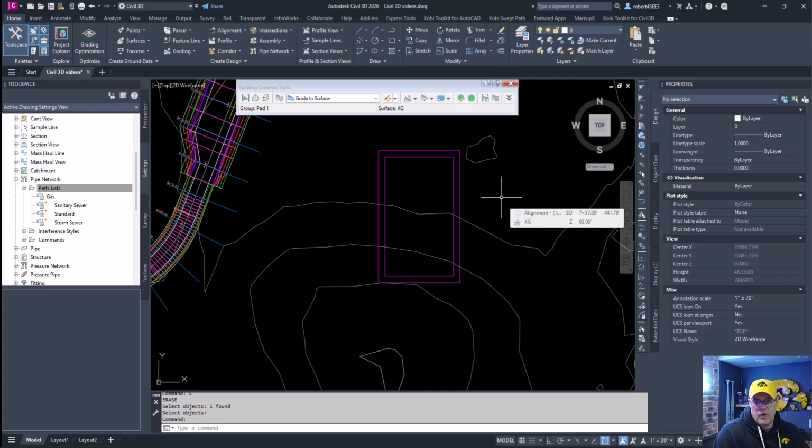All right, in this short video, I'm going to be showing you how to grade just a simple little pond here. So this first inside cell here, I'm going to grade downwards, say a 3-to-1 slope for say 10 foot. Then on the outside, I'm going to grade, say 3-to-1 for cut and 4-to-1 for fill. And I'll look at a transitioning also.